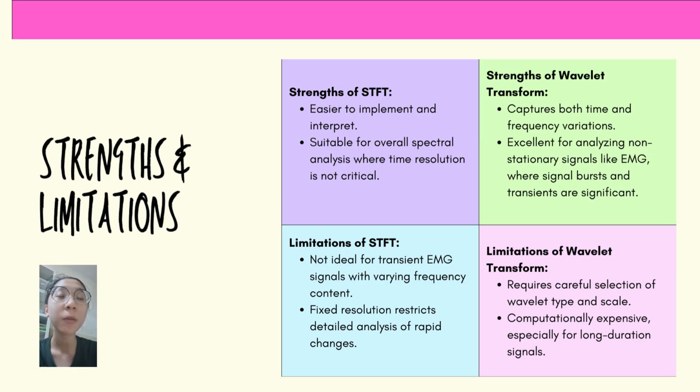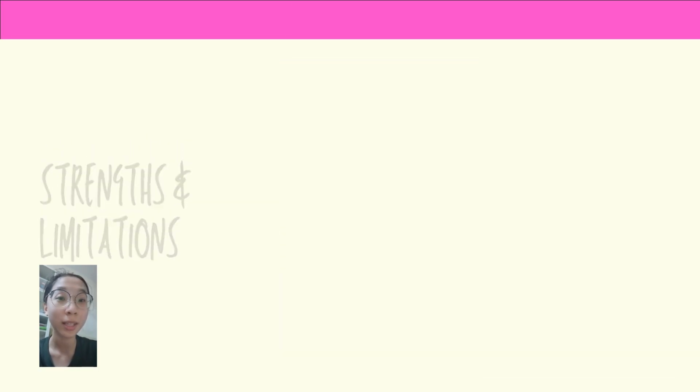The limitations of the STFT include being non-ideal for EMG signals with varying frequency content, and its fixed resolution restricts detailed analysis of rapid changes. Meanwhile, the limitations of the wavelet transform analysis are that it requires careful selection of the wavelet types and scales, and it is computationally expensive, especially for long duration signals.